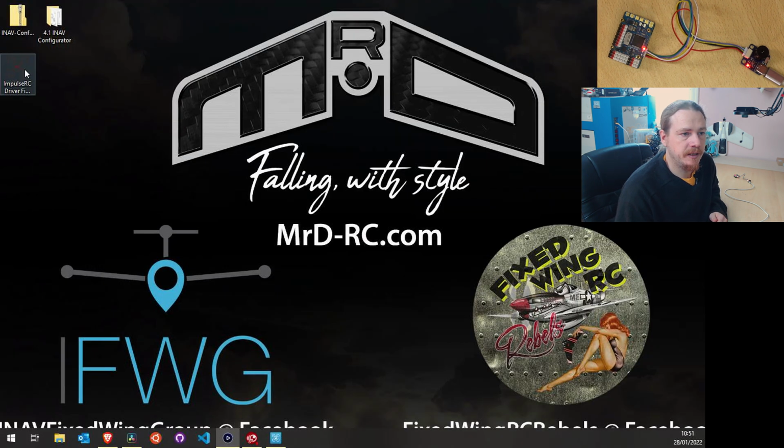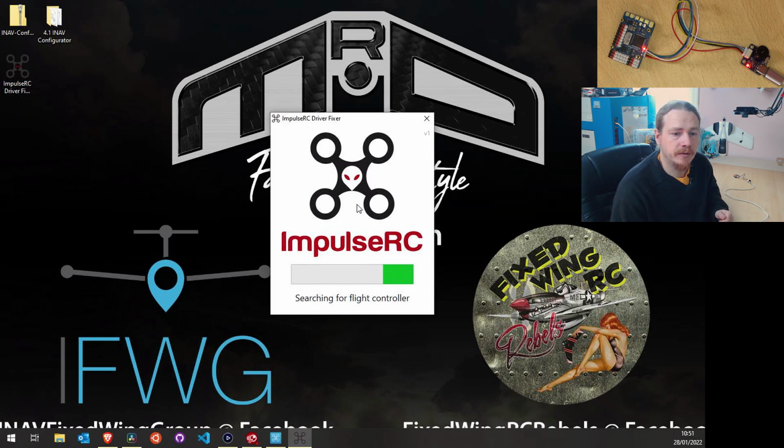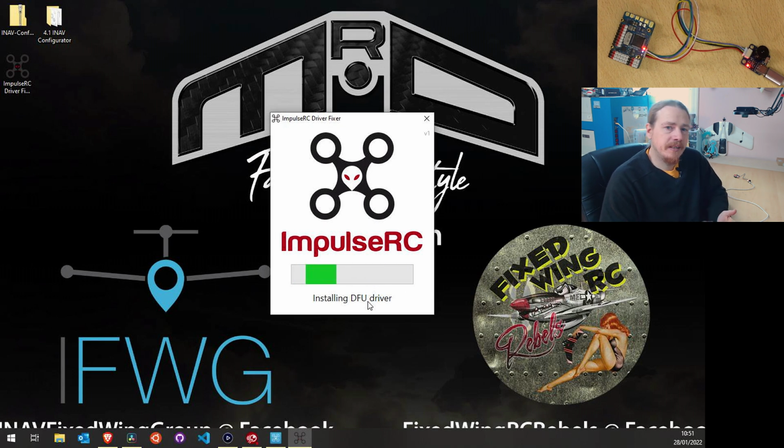So here is the Impulse RC driver fixer, and you just double click to run it. If you do get any messages like this, just OK it, because it is safe to run, and it will just find the flight controller, put it into bootloader, and then exit, so that we're at a stage where we can just flash the firmware. You can use another program called Zadig, and to be honest, I just don't find it as simple or as easy to use as the Impulse RC driver fixer, so I just use that all the time.